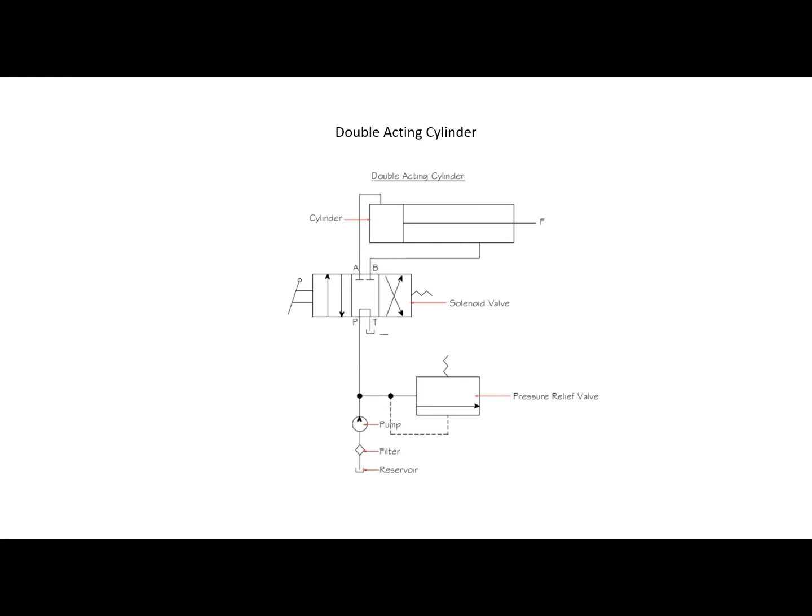When the four-way valve is actuated into the flow path configuration of the left envelope, the cylinder is extended against its load force, as oil flows from port P through port A. Also, oil in the rod end of the cylinder is free to flow back to the tank via the four-way valve from port B to port T. Note that the cylinder could not extend if this oil were not allowed to leave the rod end of the cylinder.